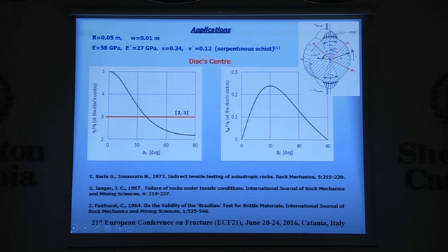These are the elastic properties, and I think here I have used an external applied load of 15 kilonewton. We have first focused our concentration at the center of the disk, this point, which, as I have told you before, is supposed to be the point of the onset of failure, according to the Brazilian test.